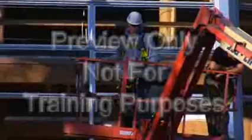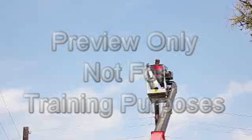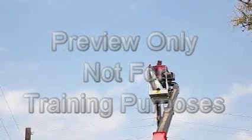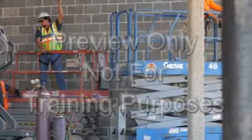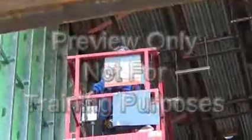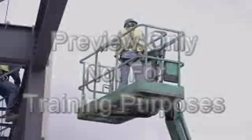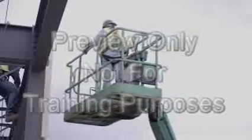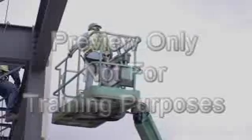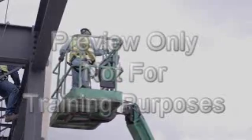MEWPs are classified into groups and subdivided into 3 different types. Group classification is determined by whether the lift stays within the tipping lines or moves beyond the tipping lines. Group A is an MEWP that moves vertically but stays within the chassis or tipping lines. Scissor lifts are an example of this group. Group B MEWPs can move beyond the machine's chassis or tipping lines, which includes outside of wheels or outriggers. Group B generally refers to boom lifts.